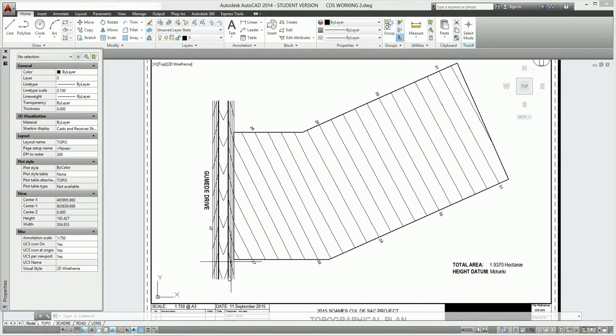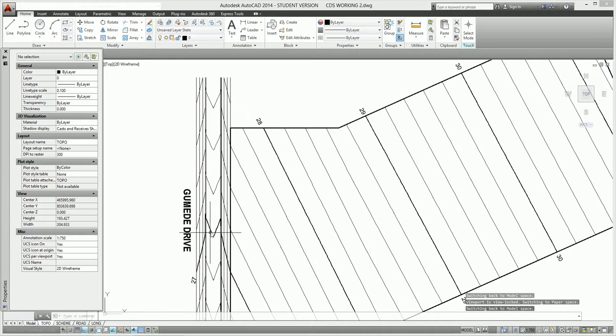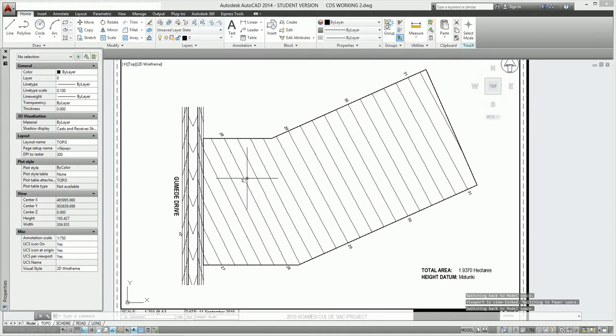So we can see, just looking at this bit of land here, that it's rising from here. I think it'll be 27 there, 26.8 there, and 26.6, possibly down to 26.4, and up here 27 and 27 here, 27.246, possibly 8 up here. The land is also rising away from the road, 28, 29, 30, up to 31.